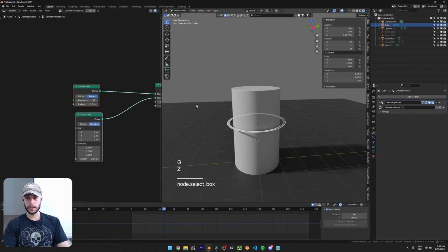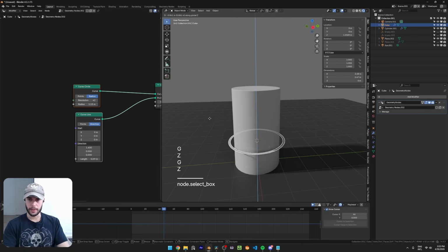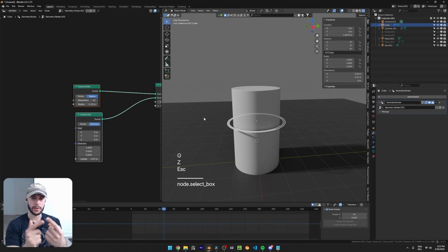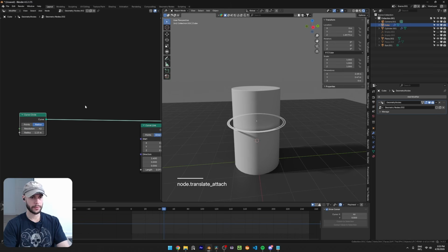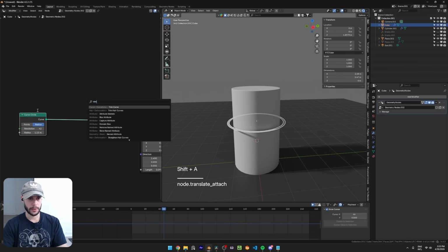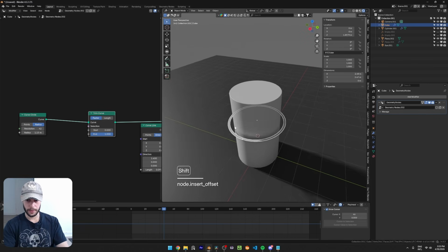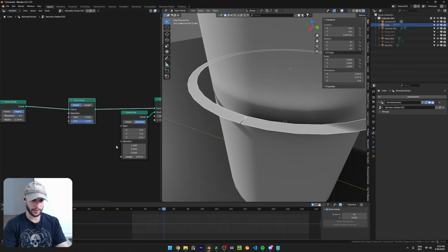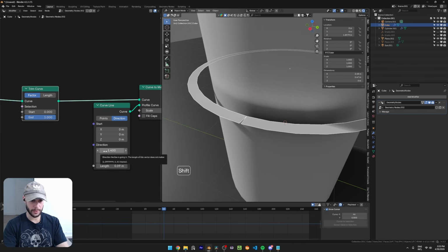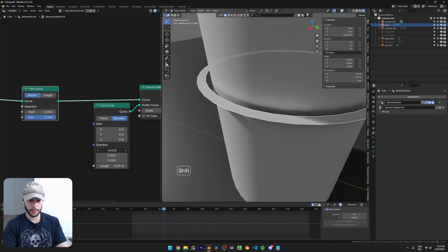Now we would like to animate this. And by animating, I don't mean just going up and down. I mean actually filling the circle around it. Go to Curve, and we're gonna use Trim Curve. There we go. So now it's easy to animate. We always get this, and an easy fix is flipping the direction, so it goes inwards instead of outwards, and there you go.